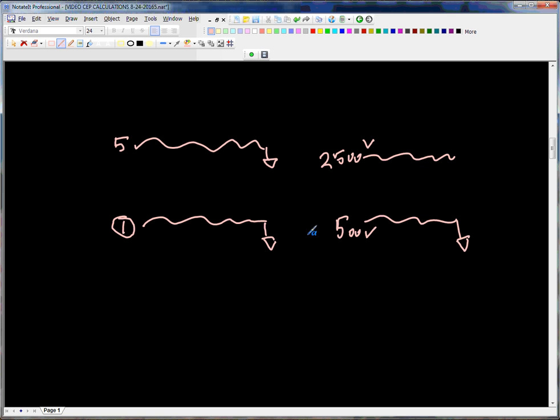This is actually how we start to look at a transformer design, especially looking for capacitance values. But we want to scale this 500 volts down to 1 volt. We have a reason for doing that. A little later I'll tell you why. So if this is 1 volt for 500, this is going to be 5 volts for 2,500. Okay?